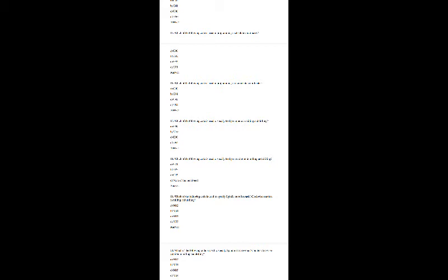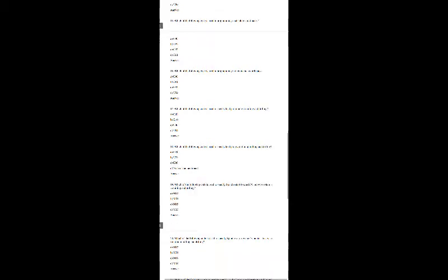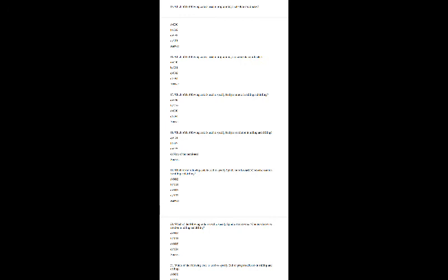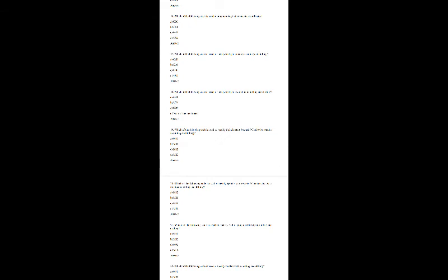While doing the programming in various examples, we have used this many times. For many programs we have used the absolute coordinate system, and in our previous example of circular interpolation part programming we have used the incremental coordinate. So for absolute, G90 is there, and for incremental coordinate, G91 is the code used. Okay, now let us see the question number 17.